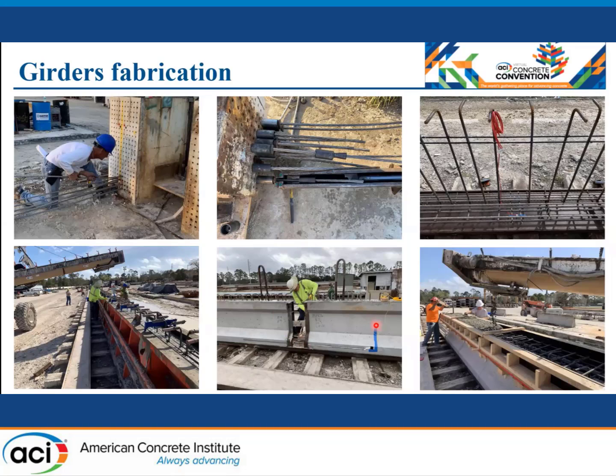In conclusion, fabrication of girders prestressed with stainless steel strands did not require any different procedure or equipment compared to the fabrication with carbon steel strands. It was smooth, very easy, and we didn't face any difficulties during fabrication.